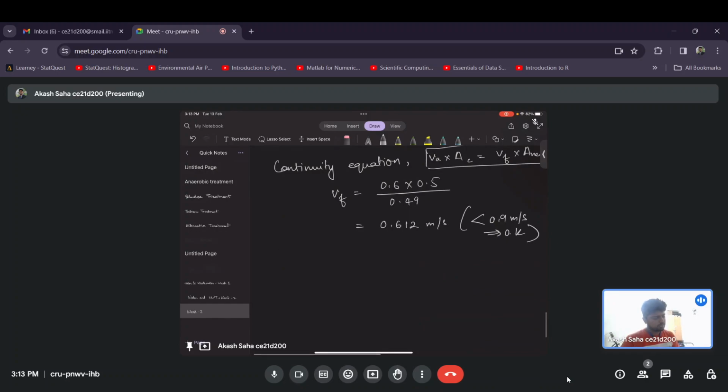Okay. So at last, I will just calculate the head loss. HL is equal to 1 by C, since we have the coefficient of discharge, so we have to take it into account. So 1 by C into 1 by 2g into V square minus v square.